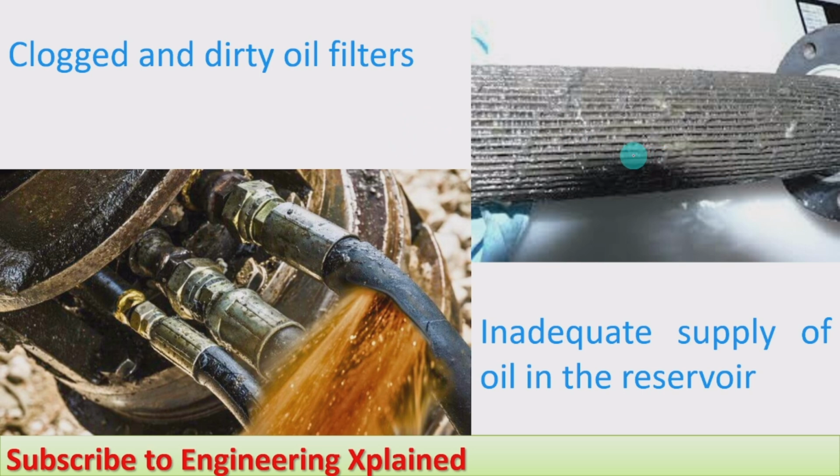If for a longer period of operation, that oil filter whatever we are going to use becomes choked, and that becomes dirty, and its efficiency reduces, and the filtering capacity reduces, and the oil flow from the filter reduces, and that's why it should be replaced frequently during its operation. That is the one reason.